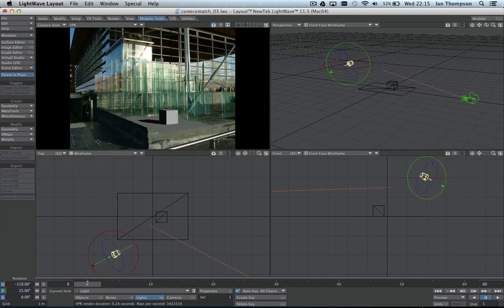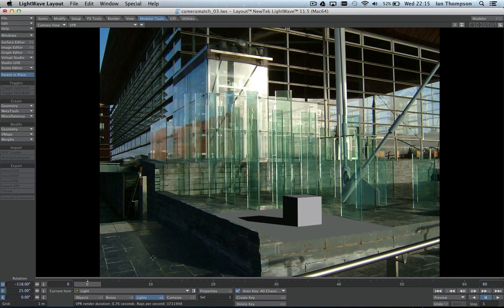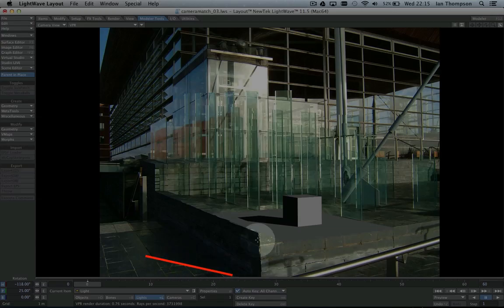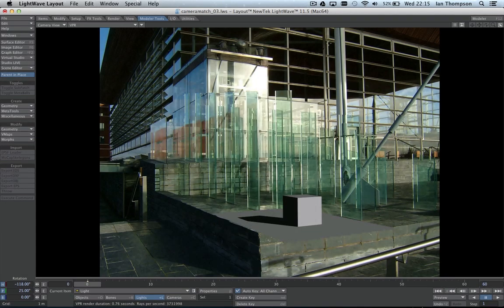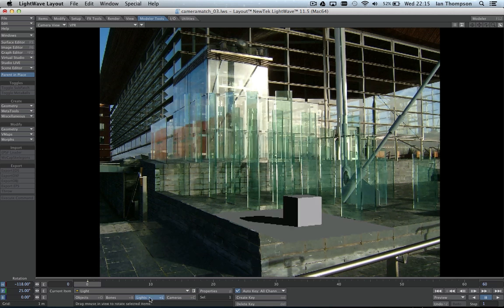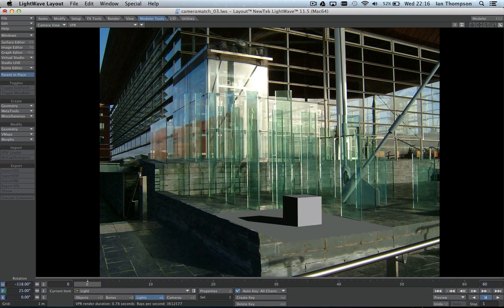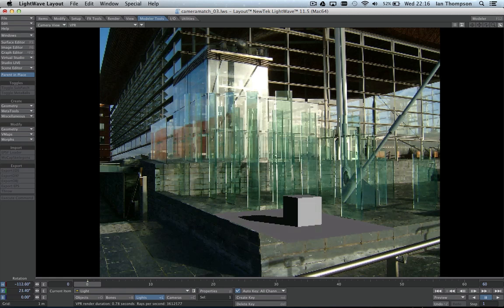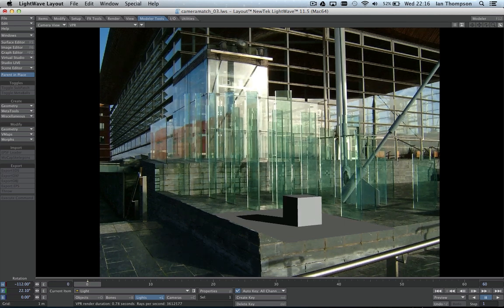We can see down here, let's just expand this again. This shadow is from the original image. We can see that shadow line there. So I'm just trying to roughly position that light so that my shadow here is at the same rough angle as that one. So my light selected down here, Y on the keyboard, and I can just move that around in real time and position like so.